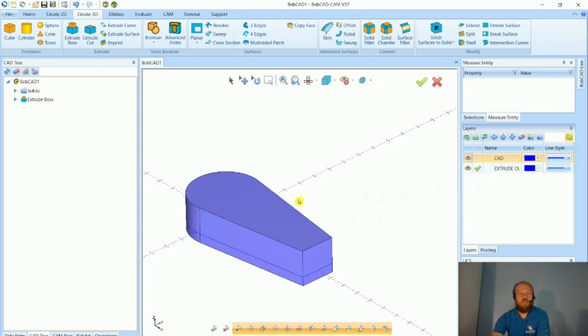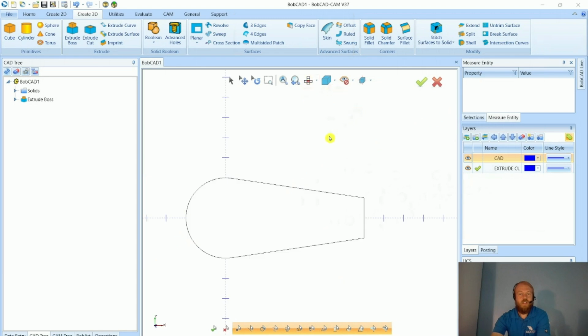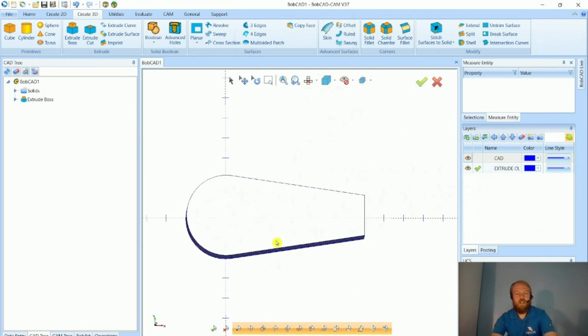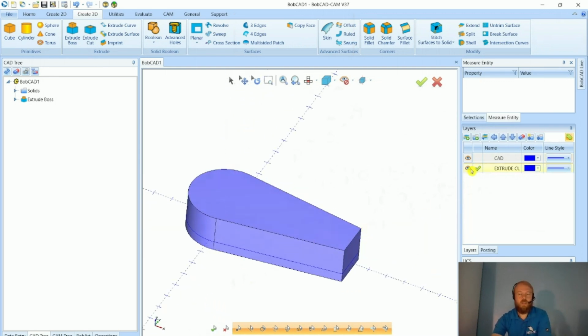So if you've been following along so far with the beginning here, all I did was create a circle. You can see with this profile, I created a circle at the center, 4 inches in diameter. I had created a rectangle out here, 2 by 2, and just went from endpoint to tangency point, sketching lines, endpoint to tangency point to create this profile. Then under utilities, I went to quick trim to trim away the inside profile shapes. And now I can hide all of the geometry on that layer by hiding the CAD layer here.